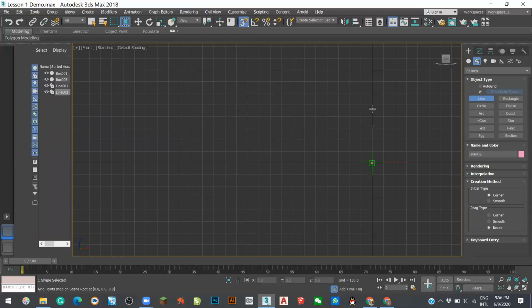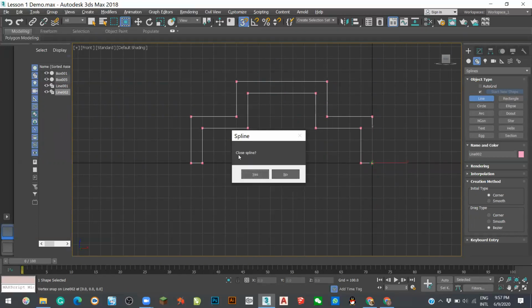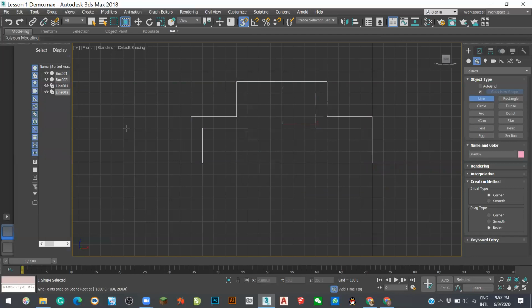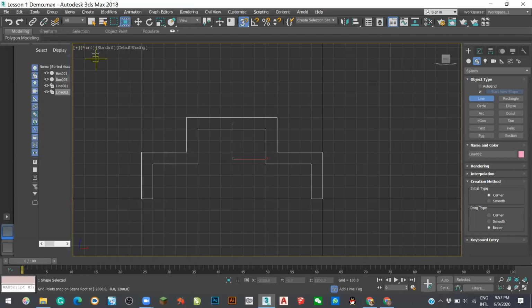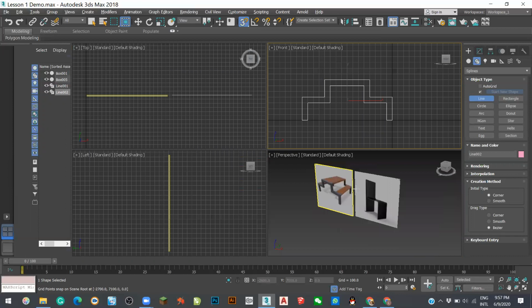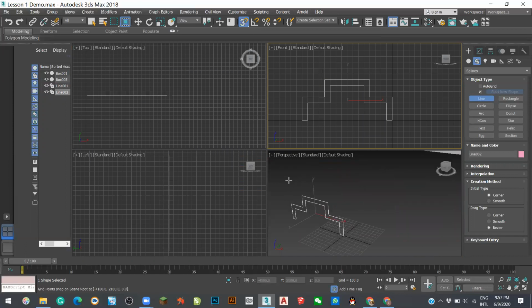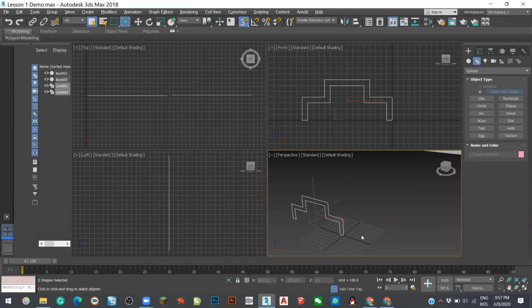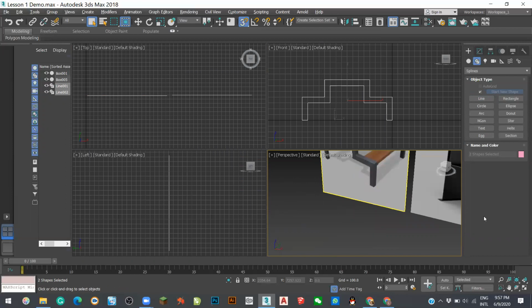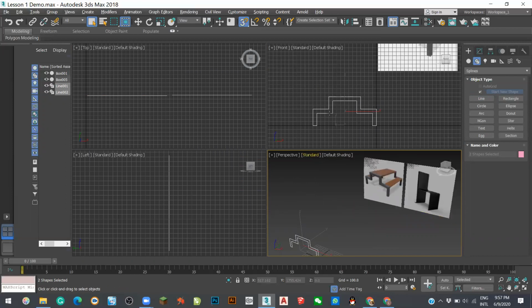anywhere. Okay, I start from 0, click, 400, 400, 400, 200, 400, 800, 600, 400, 400, 400, then 100. Click. It will ask whether you want to close, then yes. Okay, once we're done, Alt W, zoom. My object will be here. Select. Okay, next step, I will add thickness for this object.